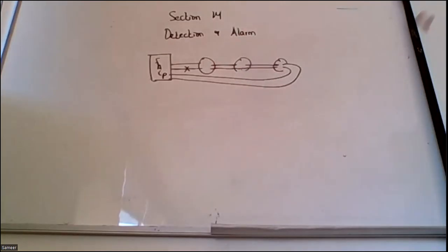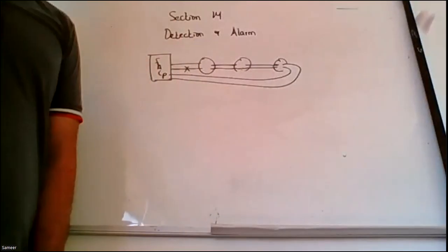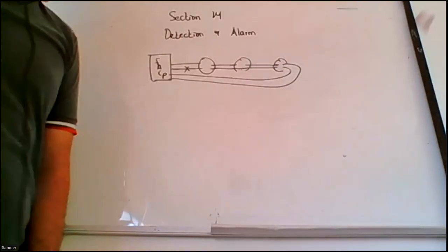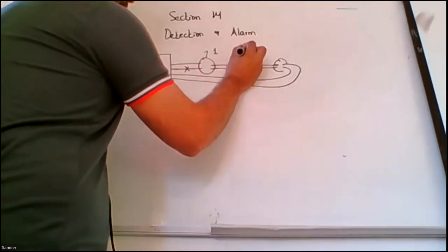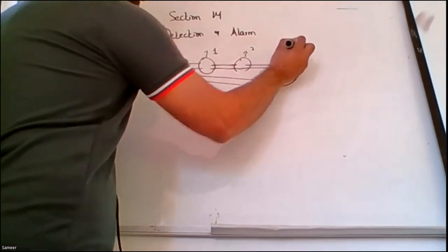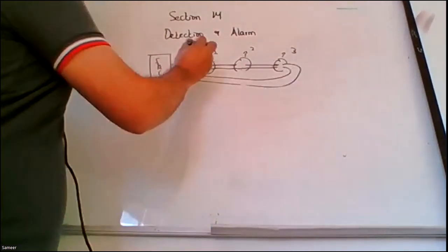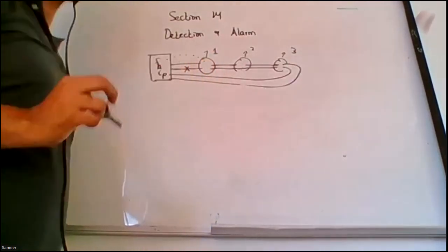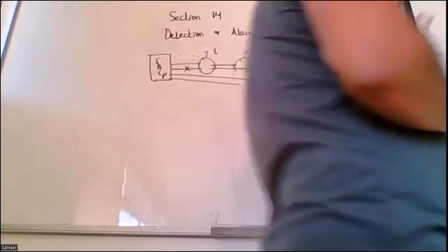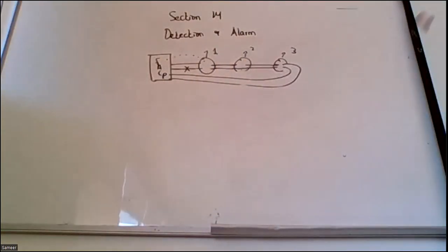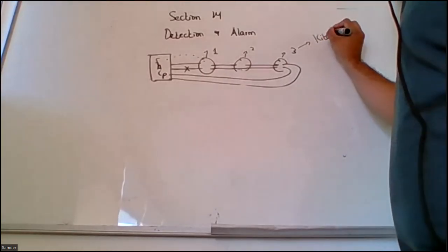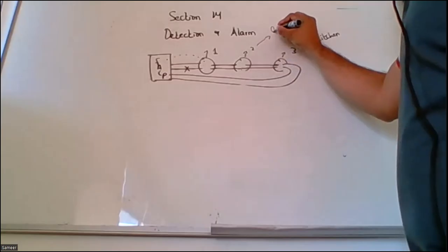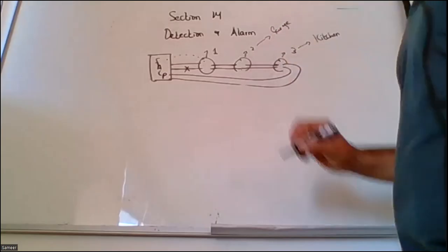Second thing is that the detectors that we use in the addressable systems are programmable detectors. I can provide them a specific coding. By a handheld programmer, I can provide a coding of 1, 2, and 3. Now this coding is directly given to the control panel, and it stores it inside. I can change these numbers to alphabets by using a program defining tool. I can change this 3 to kitchen, 2 to garage, something like that.